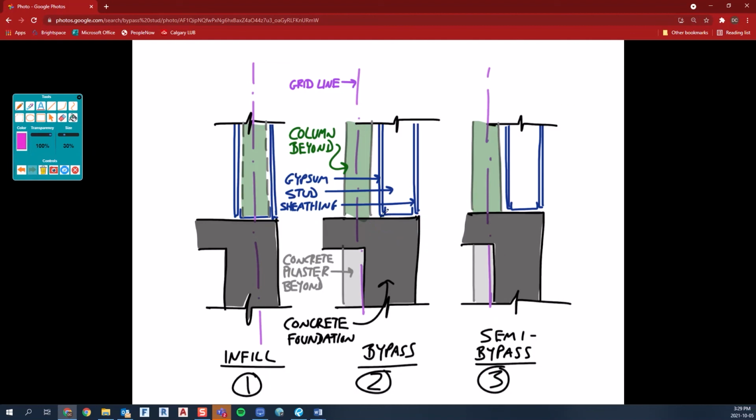So you still, the loads coming down this column are now not sitting on the foundation, right? They're missing it. So what ends up happening there is you have a pilaster in the parkade or in the basement below. So in plan view, if that's the foundation wall, you would see something like that, okay?